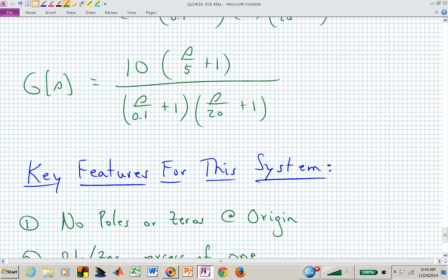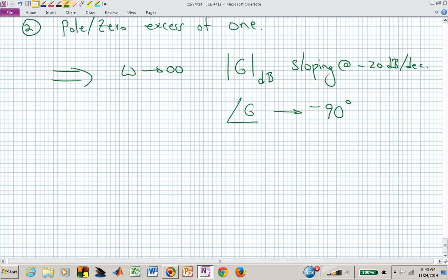That gets dominated by the 1 in each of those factors. And the log of 1 is 0. All of those factors, other than the constant sitting out front, don't contribute anything at low frequencies relative to the magnitude, which is why we factored it into this time constant form. What's the magnitude of that at small frequencies?